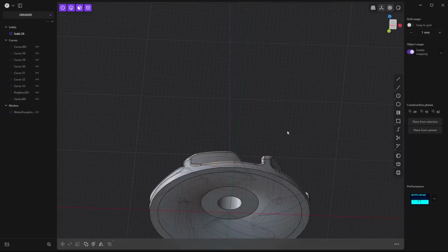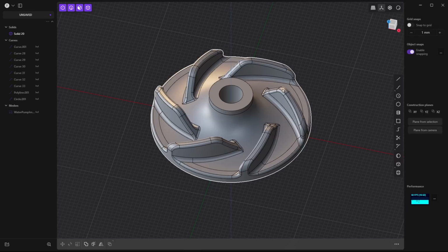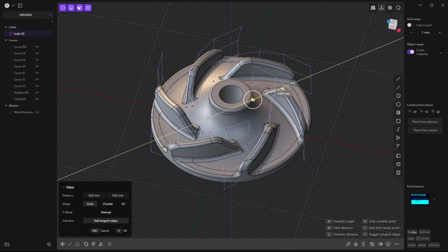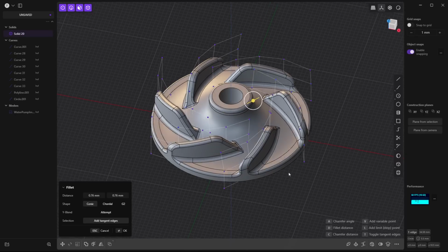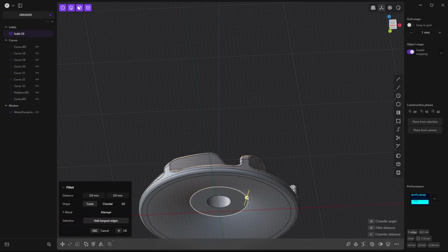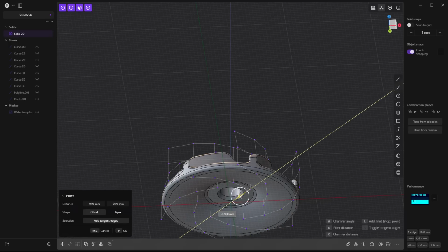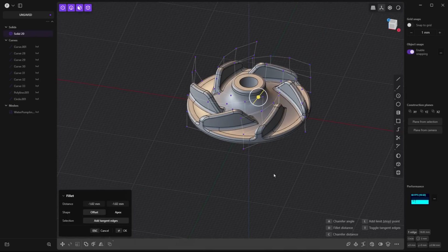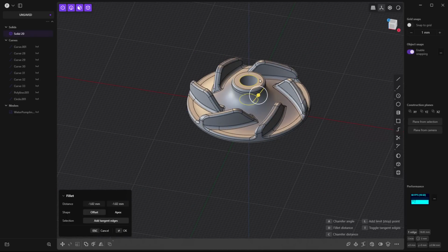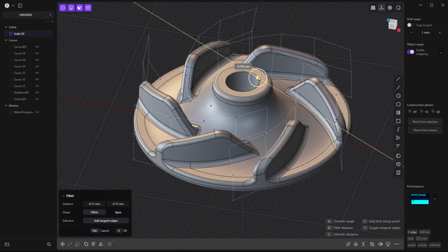Now, I did mention that this actually has a square profile in the top section. I'm not going to put that in this model, but you certainly could. And then if you want to add any other details, so this is actually rounded off in the model, and so is this bottom edge, it's kind of rounded. And this section here, and then there's a little bit of a chamfer there, and a little bit of one at the top, probably not that big. Let's go ahead and remove that one, and then we'll just add a little one here.